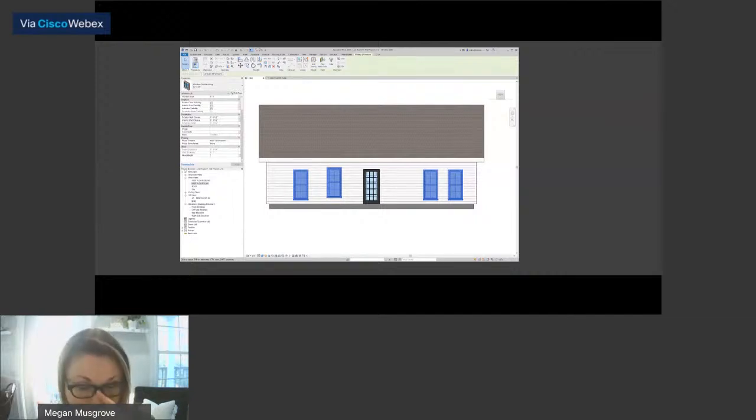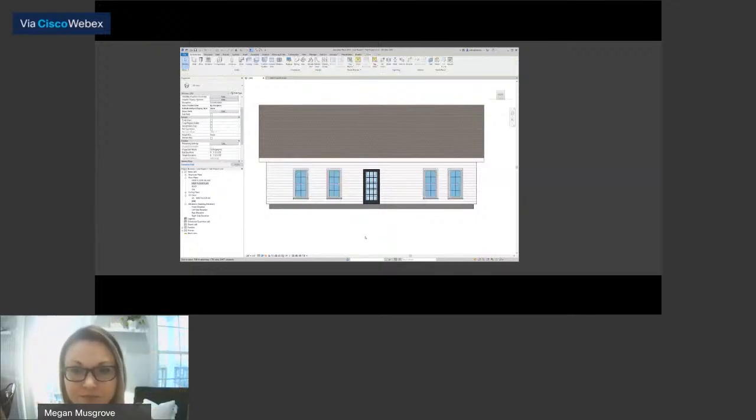So what we're going to do, we're going to put this at 80 inches or 6'8", which 7 feet is technically the standard, but I will very often put them at 80 inches so that they line up with the top of the doors, because that's standard door height, and then it just gives you a clean line around the room. Sometimes we do different things, but that's a good general rule. So we're going to type 0 space 80, enter, 6'8", and we're going to hit apply. And then that just made all those nice and neat.